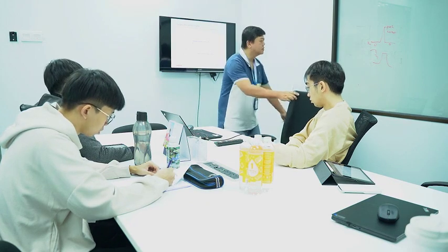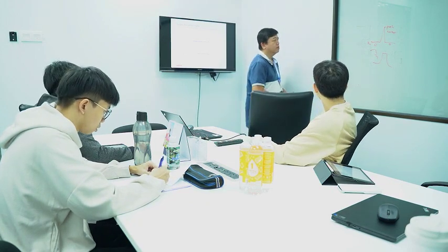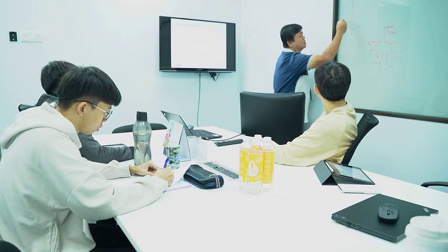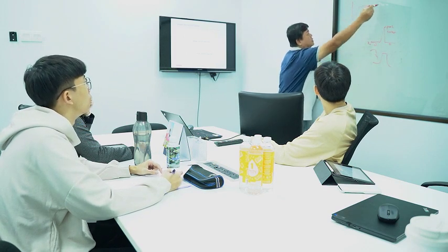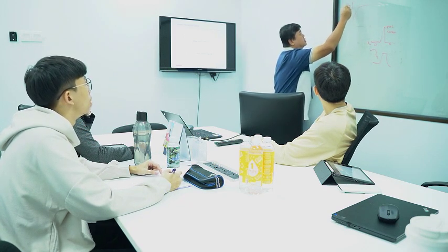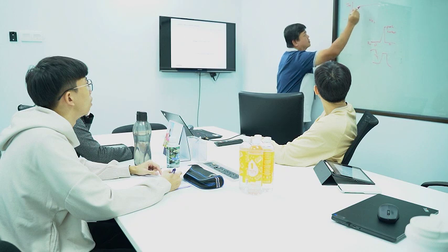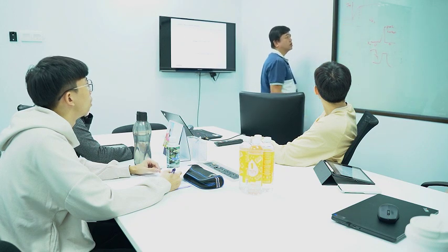What is an example of a current source? Like I mentioned also, when you bias a MOSFET transistor in the saturation region, that basically is a current source, right? You look at the thing here, right? Your bias here, this is IDS versus VDS, no? Starting from here, the current is almost constant. That's why I call it a current source, right?